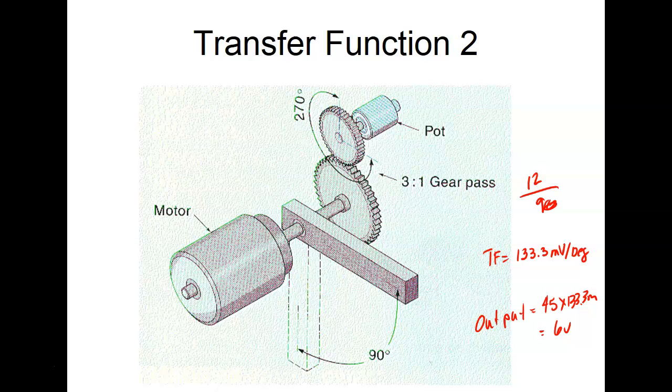So for the person that's bringing this voltage in, if the PLC's got an analog input, and we've got two, the CompactLogix that we have has several analog inputs on it. The 1100 that we have in PLC 1 has 2 analog inputs on it. The Siemens 1214 has 2 analog inputs, and then we have what they call a signal module that we put on that gives us an analog output.